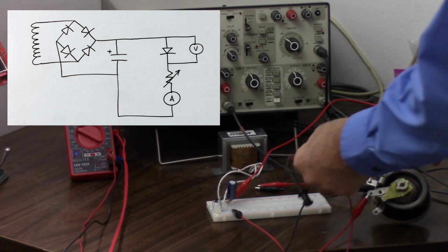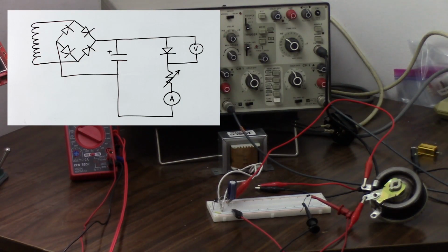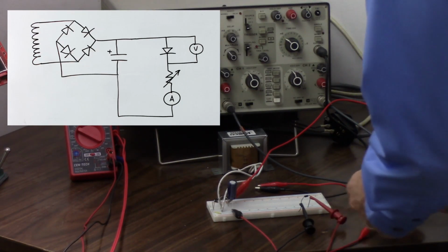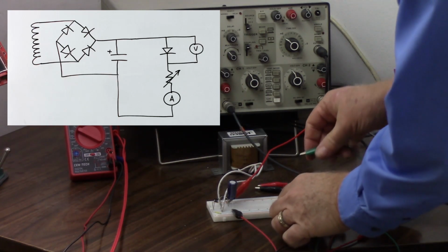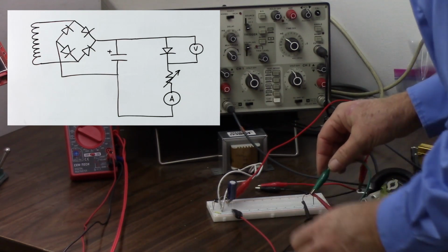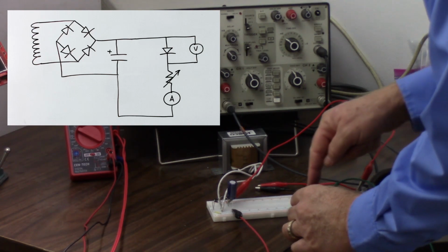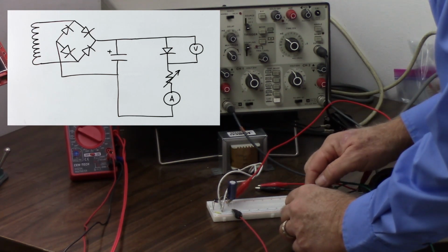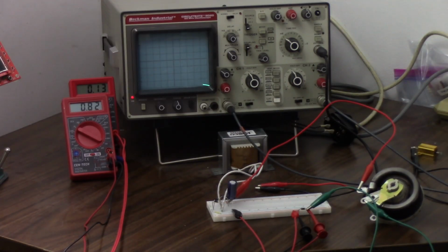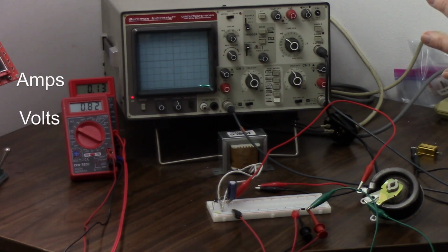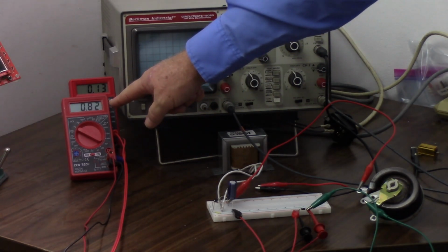Now we have to make this part of the circuit. I'm going to need another clip lead to do that. So coming off of this, okay, now we are going through the diode. Watch my colors, kind of got my colors backwards here. Okay, so we're going through the diode, current is going that direction from the anode to the cathode. That is correct. Okay, and look at that. Right now I only have 130 milliamps flowing through that diode, and I already have 0.8 volts instead of 0.7.